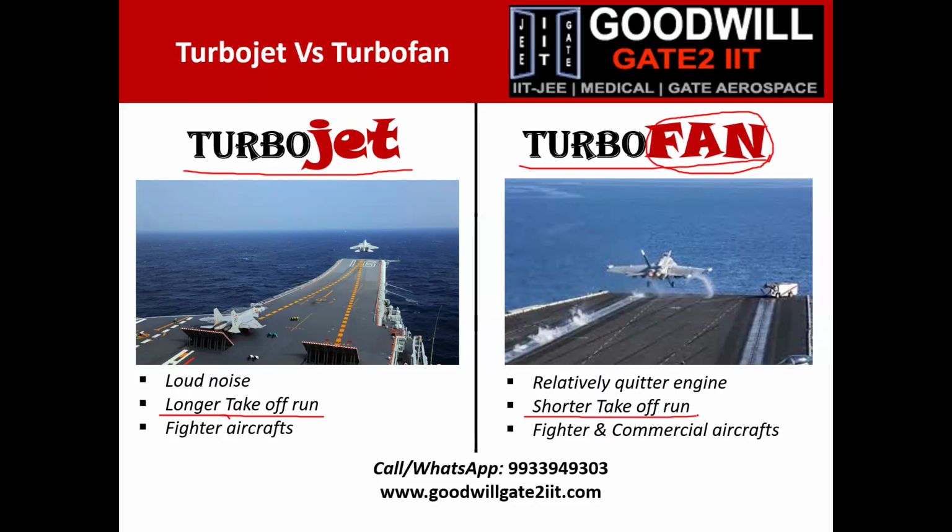This is one of the reasons even in fighter aircraft you see low bypass ratio turbofan engines. Keep one thing in mind: when you have a fighter aircraft, you need to take off from very short distances as well. I have taken an example of taking off from an aircraft carrier. A carrier is limited in length, right? So you need shorter takeoff runs.